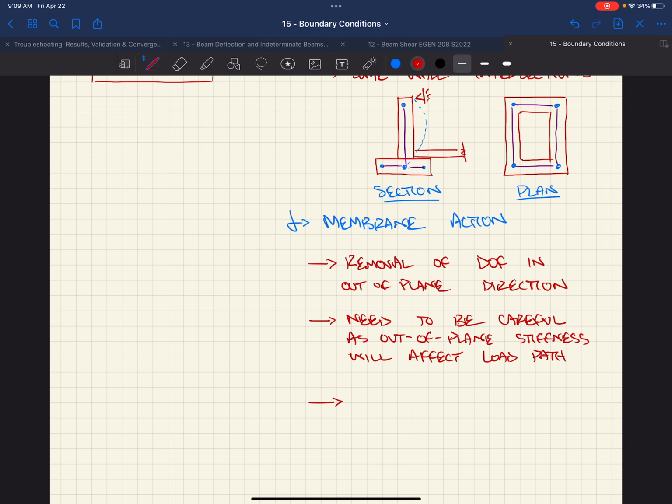So you can simplify a lot of times, because a lot of times diaphragms are really just interested in how it distributes that load in plane, right? Horizontally within the diaphragm. So you're saying for a diaphragm, you don't care about the out of plane? A lot of times you don't, but if you were designing that beam as composite with this diaphragm, you might want to consider the fact that the rotations of this diaphragm have stiffness and it's going to affect how the load's distributed.